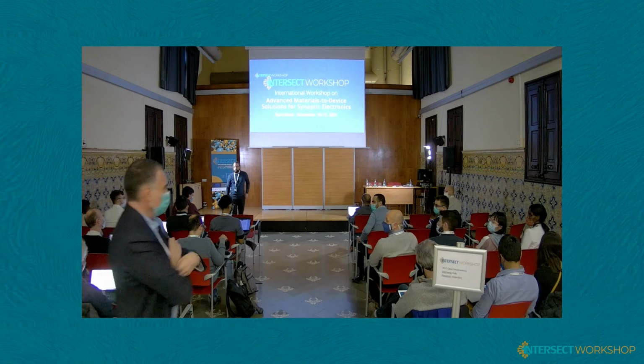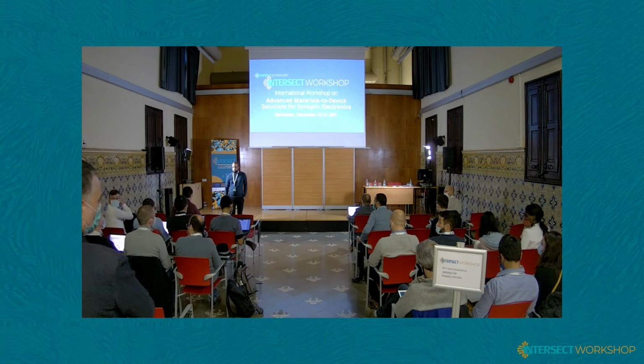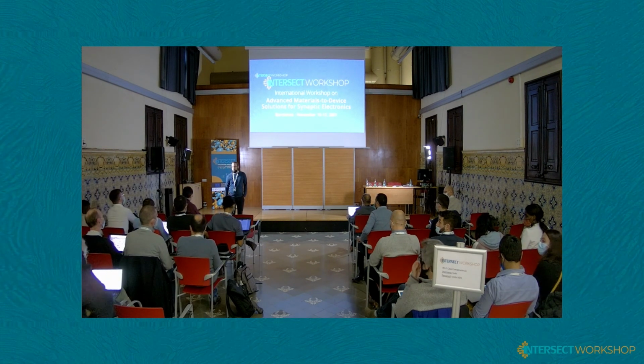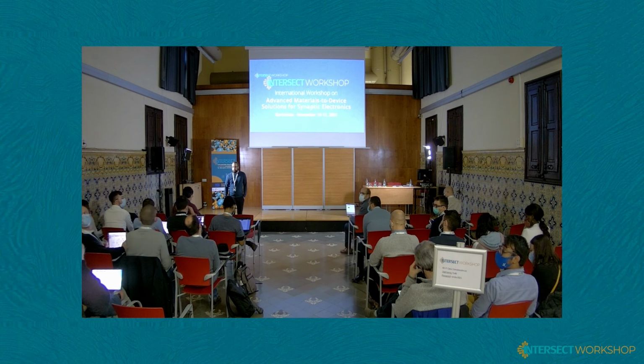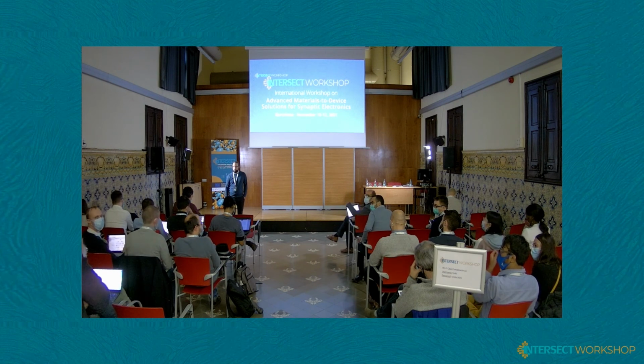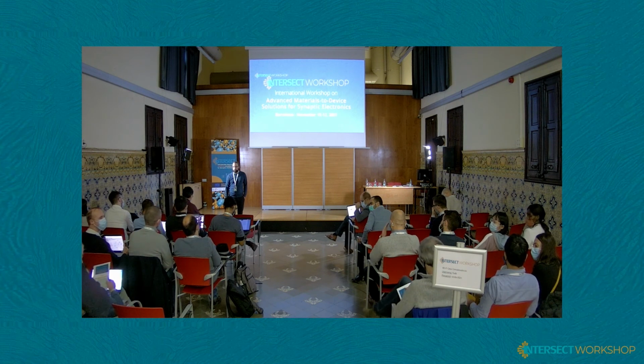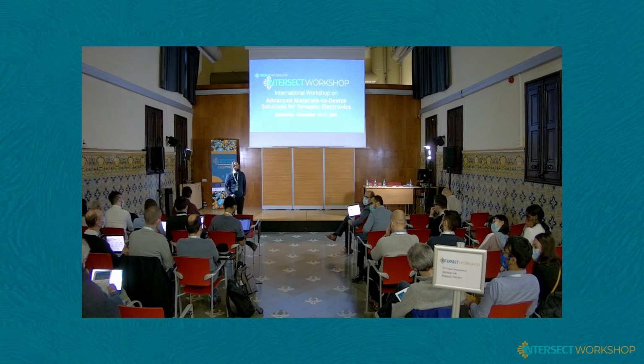Thank you, Johannes. In the first presentation from Global Foundries, we saw that there is a pool of electrons accumulating in the potential well formed by the interfacial layer and the conduction minimum of the ferroelectric. I didn't see that in the model that you were presenting. Could you comment on that?